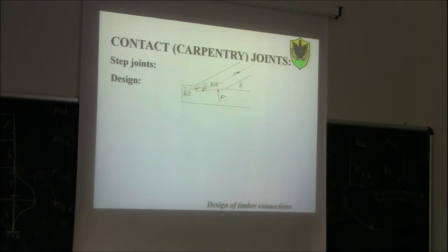Okay, that's correct, exactly. So when F second moves towards the edge, the neutral axis cuts the cross section. Meaning that what we can expect in this situation, which is also called large eccentricity, as you remember. What kind of stress can you expect on this side here?